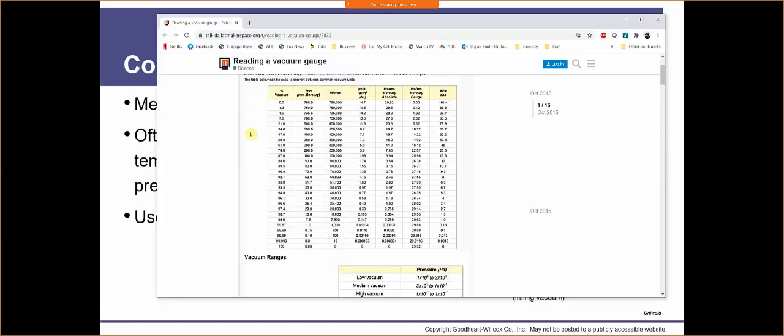All right, so what we have here is our percent vacuum. Really, what I'm looking at is, let's just say our PSI, okay? We know PSI atmospheric, what that all means. Actually, let's go to gauge. Now we'll use, okay, so here it is, 29 inches mercury, that's what we're using, sorry. So at 0, we're equal to 0 microns.